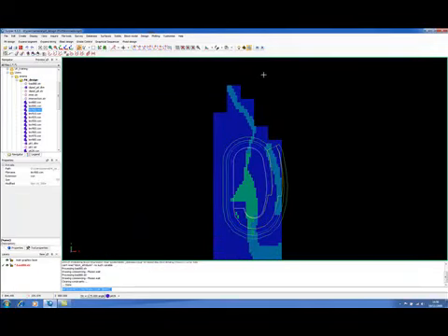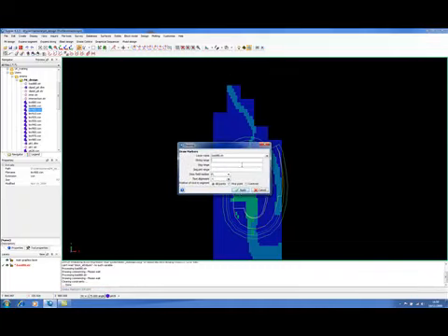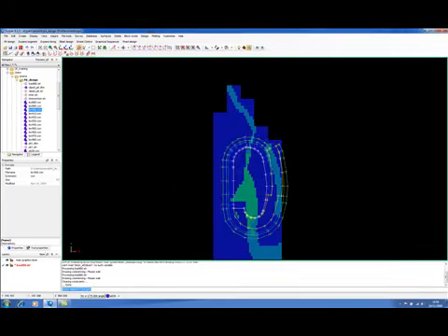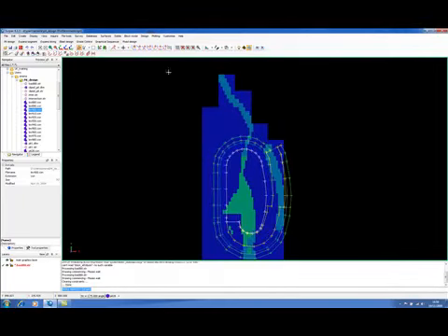At any time throughout the design, you can modify your design using basic editing tools in Surpac. If I want to capture the material on the north side of the pit, I will simply move the points.